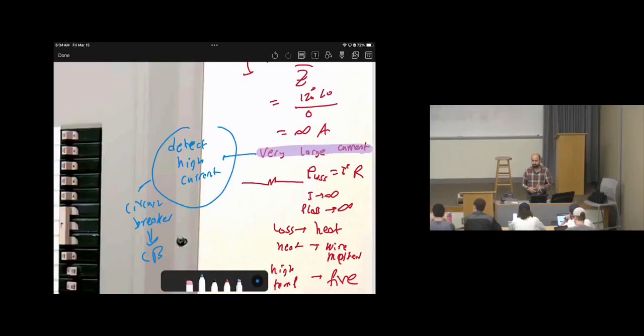So if, for example, someone goes to the wall plug and tries to connect live and neutral together to make a short circuit, this is dangerous, yes, of course. But do you think you will be electrocuted? If you have a good protection system, the circuit breaker will trip automatically without harming you. That's what's supposed to be. I'm not telling you to try it and do the short circuit by yourself, but that's what's supposed to happen. The response of the circuit breaker should be within a few milliseconds.